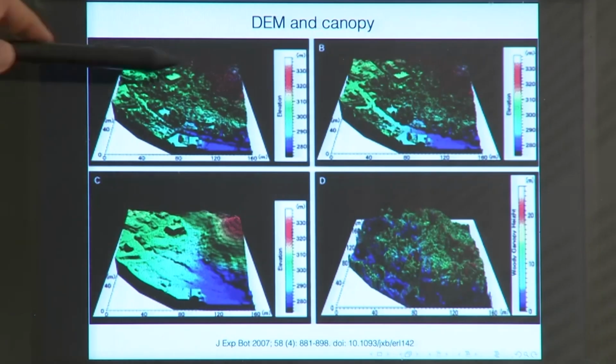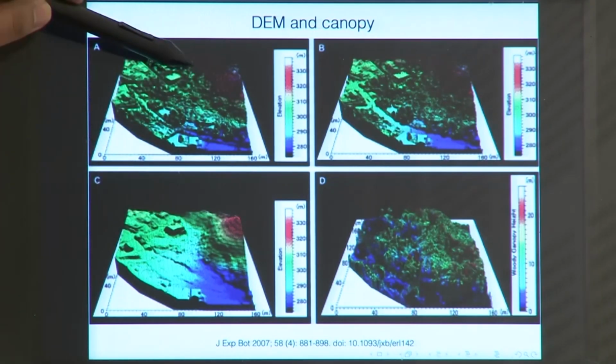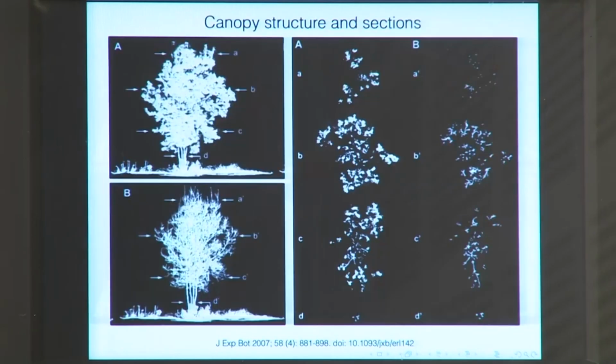In this case you can see where your trees are lying and what the height of these different trees is. So, as we talked before, you can find out the DEM, you can find out the DTM, you subtract the DTM from the DEM and you get the height of the canopy. So, one very good application is to find out the canopy and the height of different trees in different areas of the forest. This makes for a very good and a very fast survey.